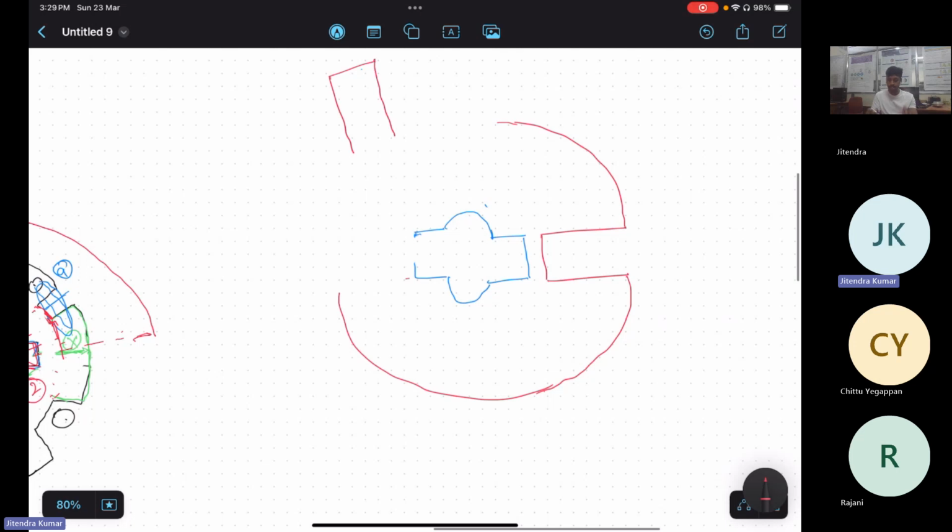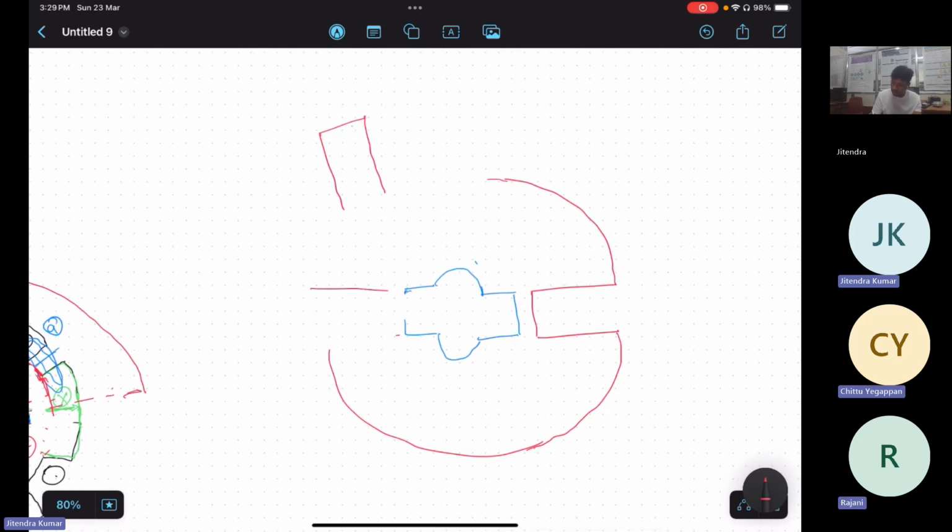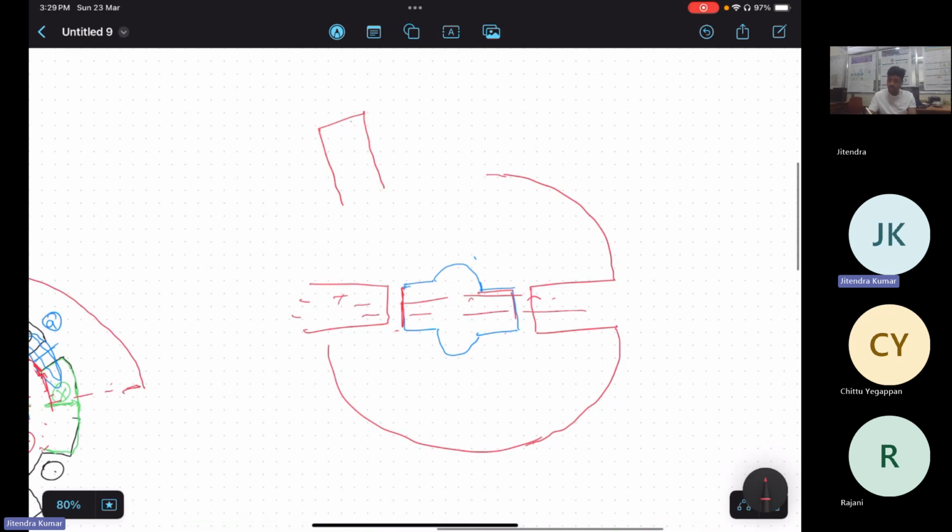Right. So once it is aligned, let's suppose it was made like earlier. This position is locked, right? And no other poles are there. Only two stator poles and two rotor poles are there. Then once they are aligned, the strong magnetic locking is there. Now the next stator tooth or next rotor pole should be available so that if the switching goes to the next phase, that should attract the rotor pole. And the switching should be off here so the stator MMF could be eliminated and the next phase should be turned on so that it moves to this position. Okay? Yes, sir.